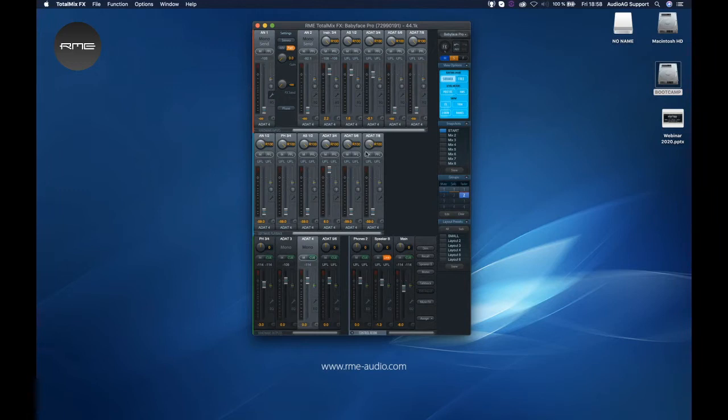Can you show that again? I forgot to share your screen. Okay. Well, let me start. Now I have something connected, a microphone. Yeah, it's a test signal, and I have a gain up here. If I want to connect a microphone preamp, I switch off the phantom power, of course, and I take down the gain. Now I can connect a signal to my input. Now, if the preamp is very hot, it means it has a very high signal. You can even pad the signal, so you can lower the signal without a loss of quality. That's how you connect a different preamp to a Babyface.